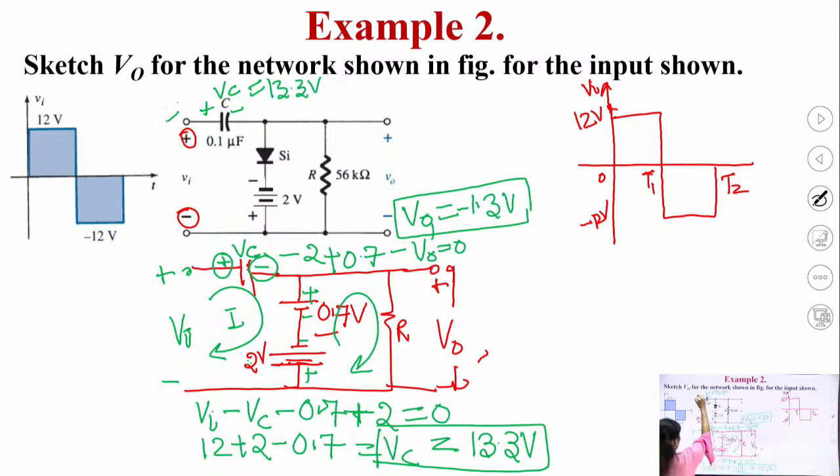So, it is minus and this terminal will be at positive potential. So, now this minus and this minus both are the negative sign. So, this will make your diode reverse biased or forward biased? Anyone? Reverse biased, because these both are the negative sign. So, the diode will be in a reverse bias position, and if you will draw the equivalent circuit, how will you draw it?